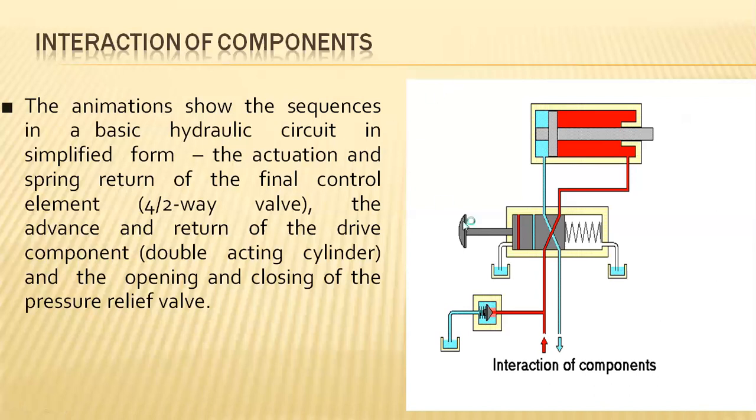And next one, if you release the external pressure on the push button, the tension caused in the spring will get into its original position by extending. At that particular time, the original connections which are made here will come into force. The fluid which has the pressure will be entering into the right side direction, and the piston passes towards the left side movement, and the already entered fluid in the left side direction will be coming back to the oil reservoir.